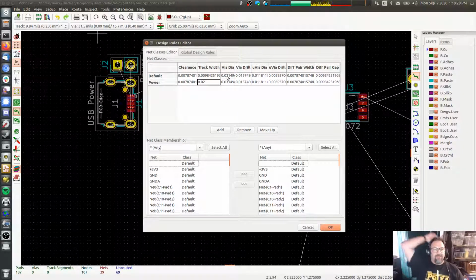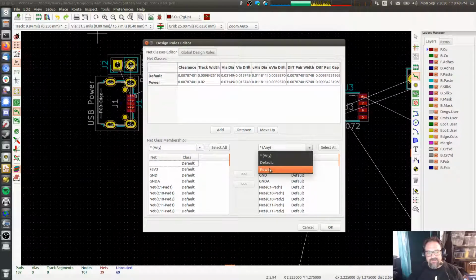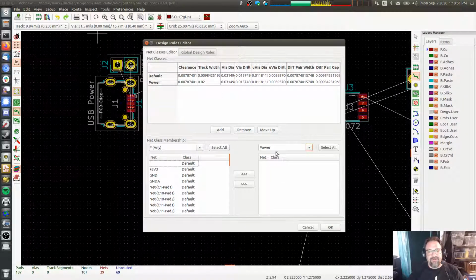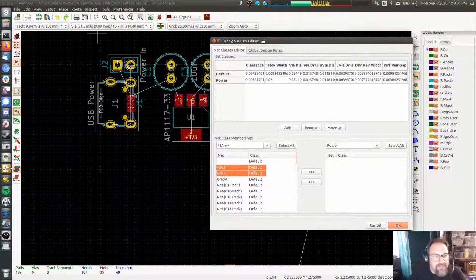So this is the design rule editor. You can have different classes of nets, and default is 0.01 inch track width. But I want to have some that are 0.02, a little bit wider. So I just create a second category of traces, called power, and then we're going to route our... I don't think ground A needs to be that, but ground definitely...